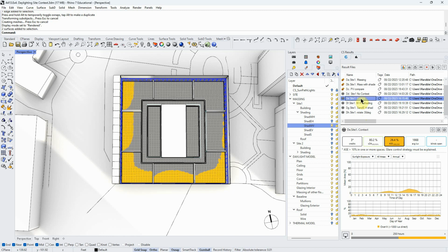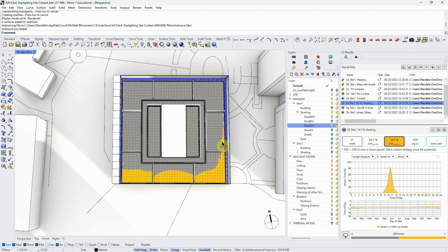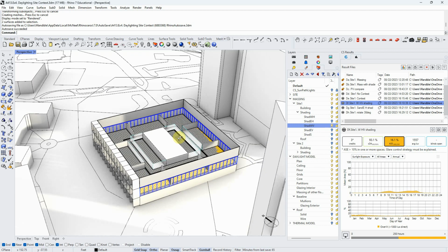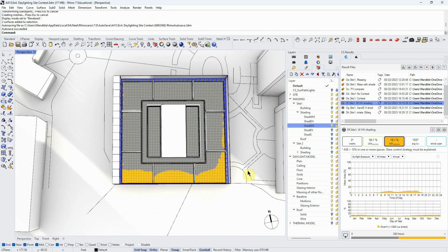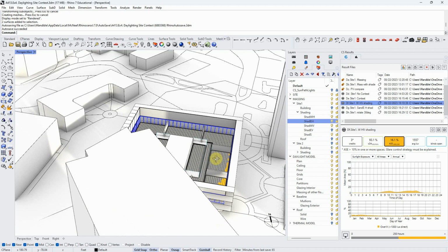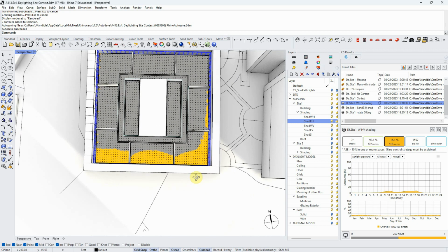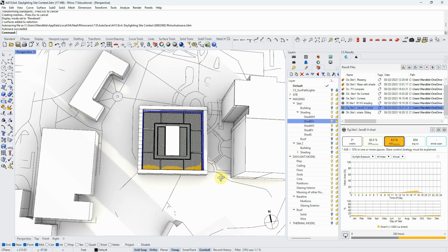And the difference between my site without shading and with shading, by adding the shading, I've basically solved the overlighting problem for the west side. And I don't really have much on the east side, or I don't think I would need to use this same sort of extreme shading layout to solve the problem here. So maybe I try just doing a horizontal, which would be these. Oops, vertical. There we go. So the next thing I tried was to just add horizontal shading on the east and the south, and that's this.